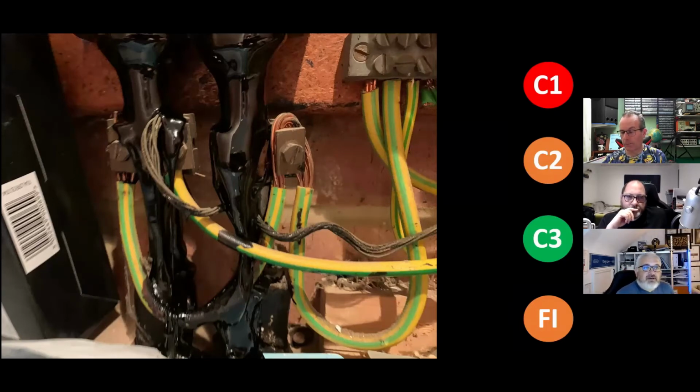You also effectively have each house on the same potential zone, because a rising potential on next door will be a rising potential on yours. If they disconnect them, you potentially lose your earthing, depending on how the earthing is configured. But as you can see here, it's a good old-fashioned mess. You've got an earthing conductor wrapped continuously around one clamp onto the other. So it's fairly evident that there's no real earth continuity on that cutout. The insulating compound on the cutout above is evidently failing because there is pitch melting all over it.